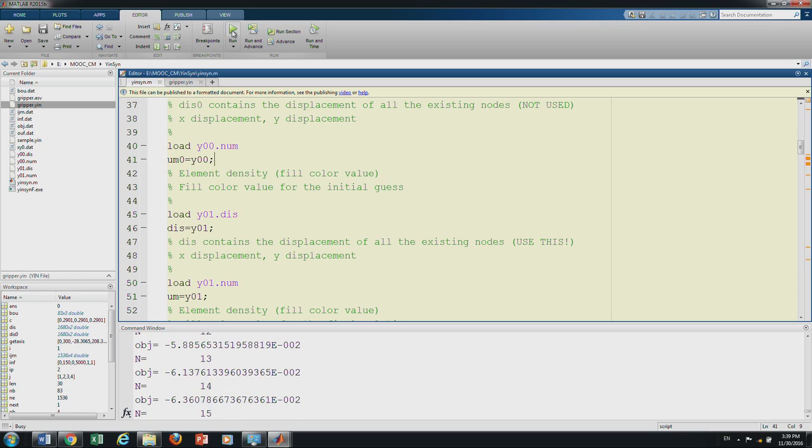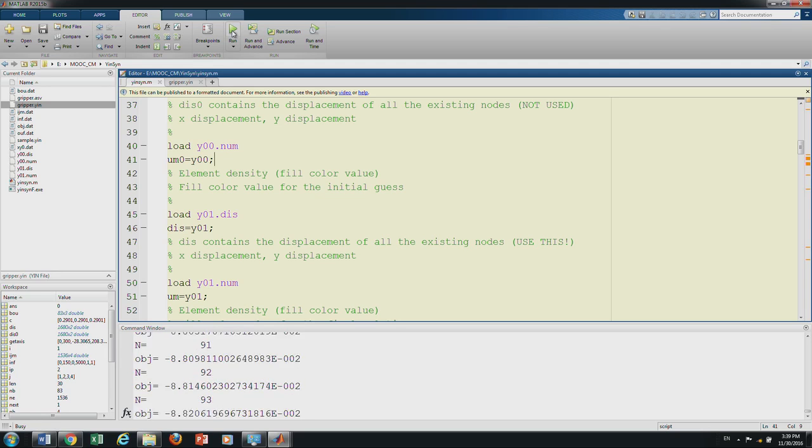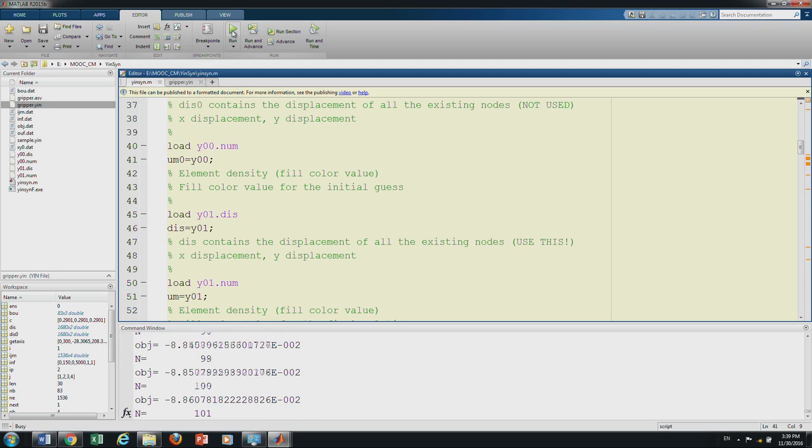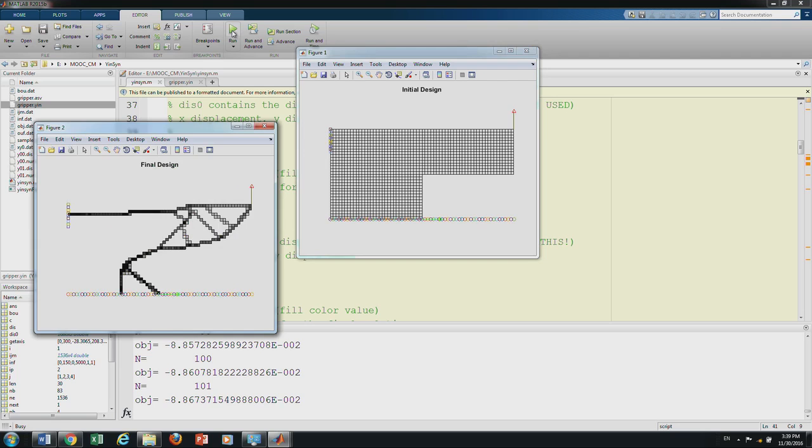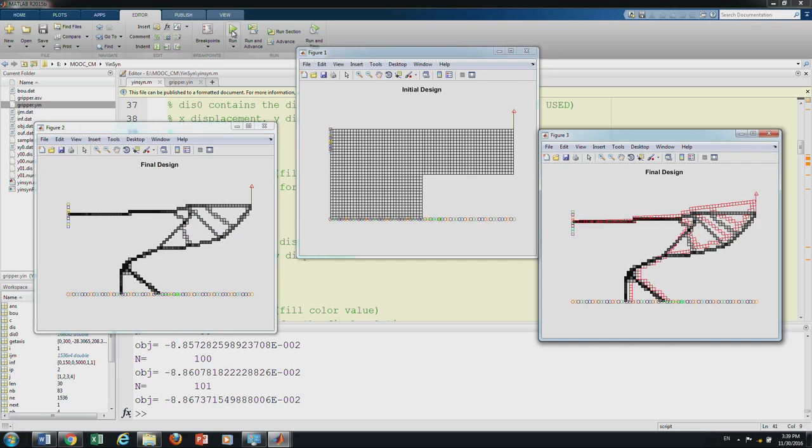Everything else is the same as the previous time we ran it, the only thing is that we are giving 30% material rather than the 10% we had given. That was a very lean design where you can actually see the skeleton very clearly. Now, it will be a fatty one where you cannot see the inherent characteristic, but whether the topology is similar or changes, we can look at it. Again, it is real time, it is trying to minimize the ratio that we talked about subject to the volume constraint that we have. It is done now. So, show the solution, it is plotting.